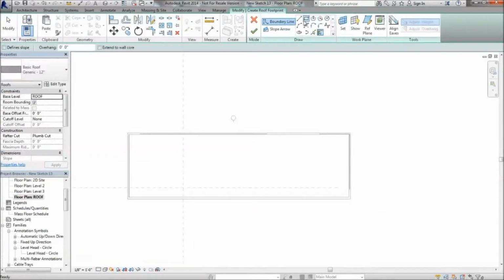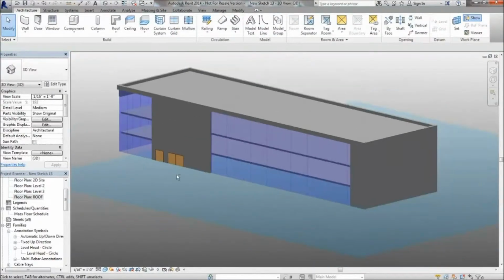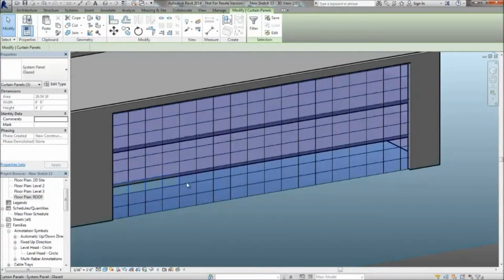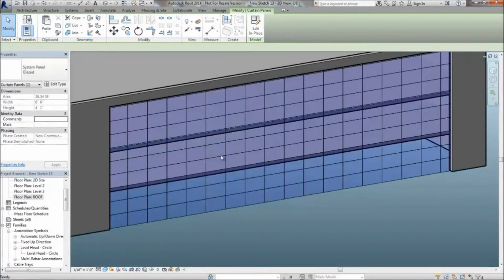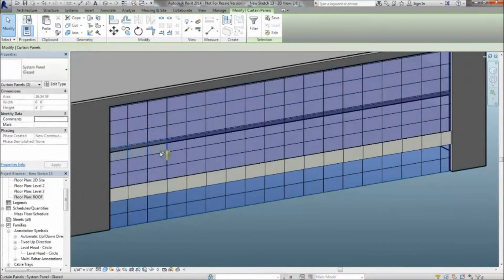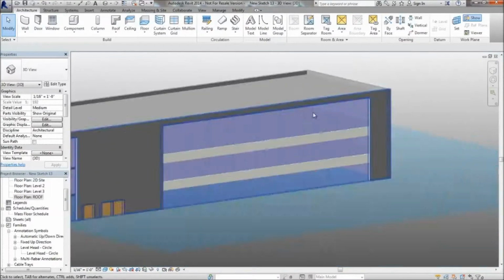Generating floor plans to deal with it at the various levels, putting in the roof, using constraints again to lock the roof to the walls so that if any geometry that you want changes, it can affect the other geometry that's associated with it. Making some overrides to various panels to put some sort of design. So just taking select panels and giving them a different glazing characteristic.